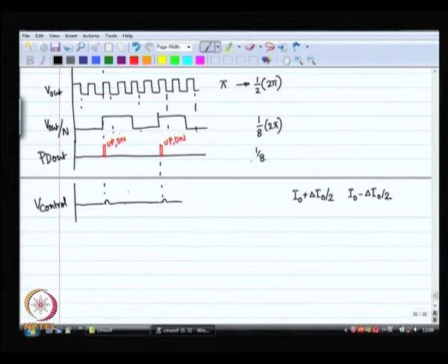So, the mismatch between the up and down currents is delta I 0. This delta I 0 is going through for what duration? The duration is the delay of my gate. This duration is the same every time.